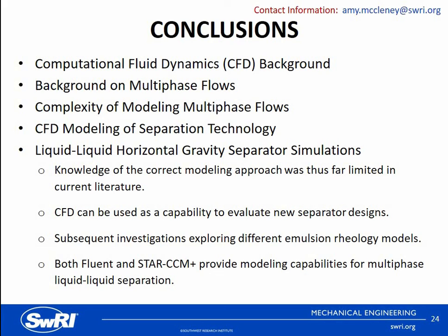Some high-level takeaways: knowledge of the correct modeling approach was thus far limited in current literature, so this study was aimed at looking at what are the best submodels out there for accurately simulating these types of flows. And we found from our studies that CFD can be used as a capability to evaluate new separator designs, but you have to be cautious of what models you use to accurately simulate the flows.